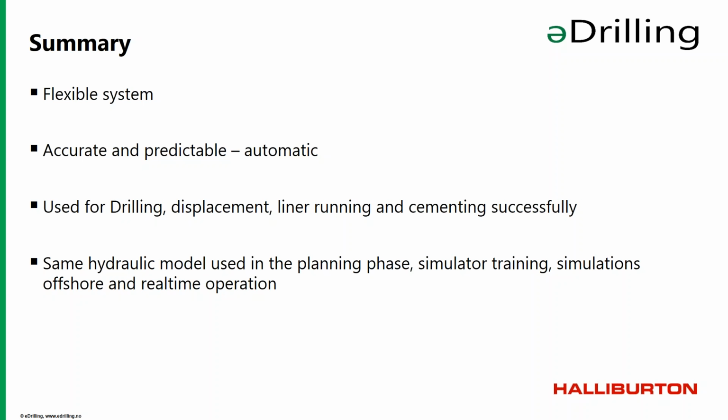Does well balance have a kick detection module? That's a good question. We don't have a kick detection module directly, but using it in an MPD system, I think Ingvild can answer that a bit better. Yeah, we have a kick detection system, but it mainly uses flow in and flow out, comparing these two values. We also have a more sophisticated kick detection system, which also looks into other parameters during